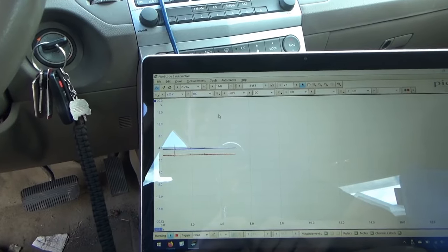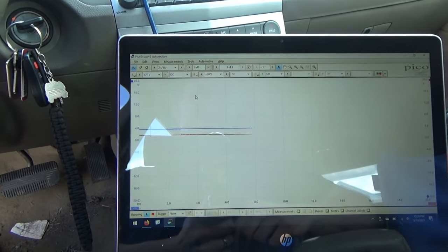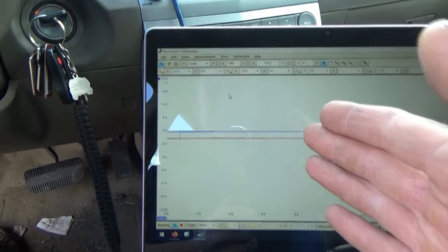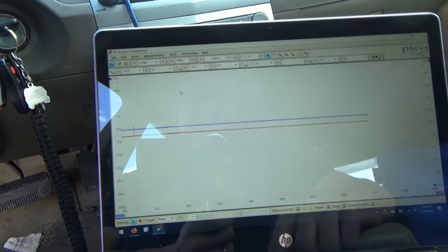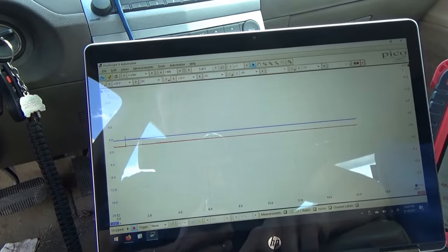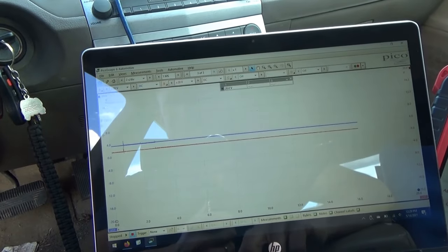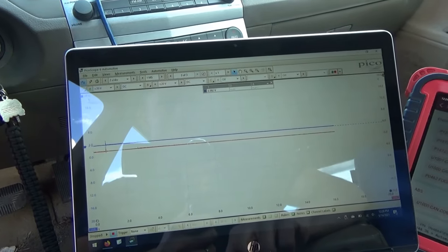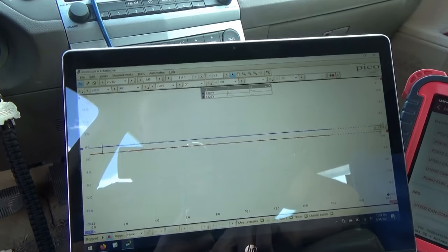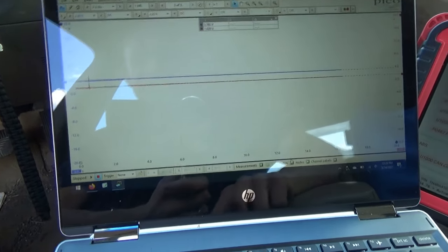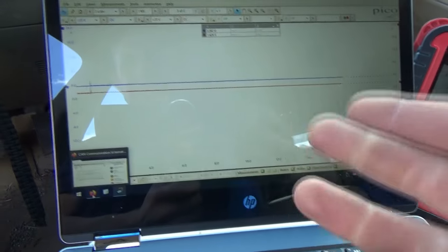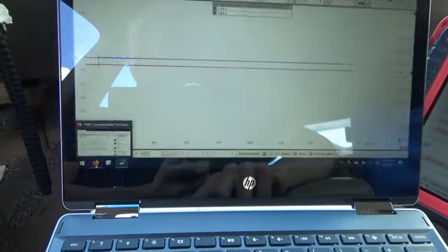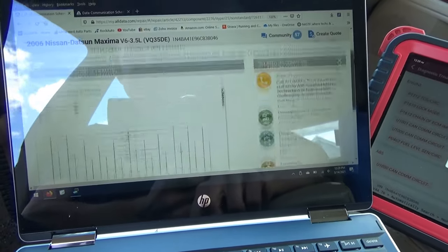Looks like nothing. Okay. So the network is basically down. We got one line at 4 volts, the other line's at... measure these guys. 3.5, 1.6. And you might ask, how can the scanner talk to these 3 modules? There must be different separate communication lines.